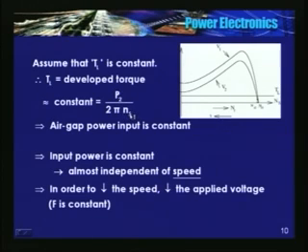Now Ns is constant because Ns depends only on the frequency of the stator supply. Therefore, if Ns is held constant, and the machine is driving a constant torque load, TL remains constant, P2 or the air gap power input remains constant.